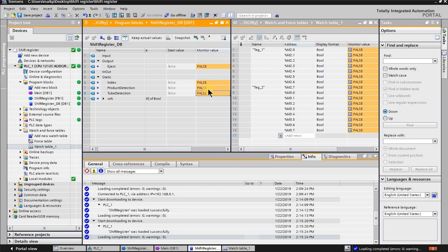So why is it that way? You might wonder, why is it not shifting further? Because we didn't reset it. Well, I can tell you why. As weird as that looks here, you have the address space 2.0 and it goes all the way through to 3.7, right? Everyone thinks, yeah, it should wander through it, and then 2.7, if we don't reset it, 3.0 all the way through 3.7, but that's not how it works.